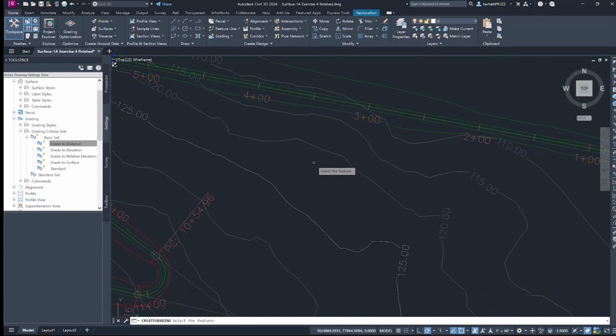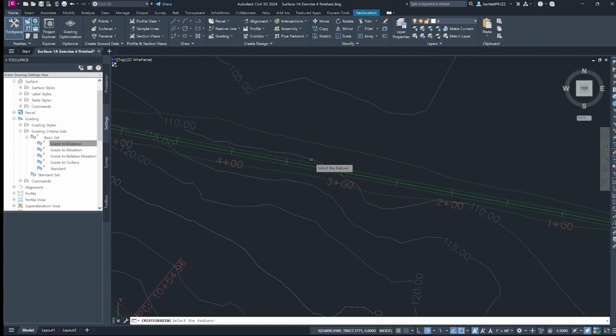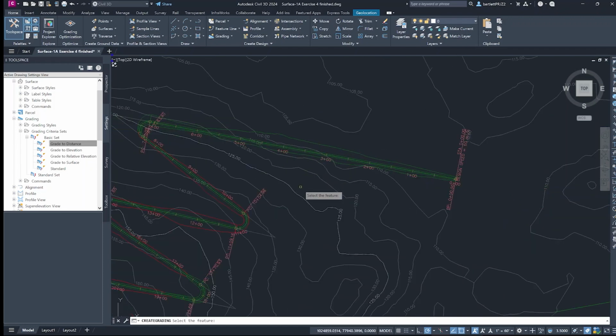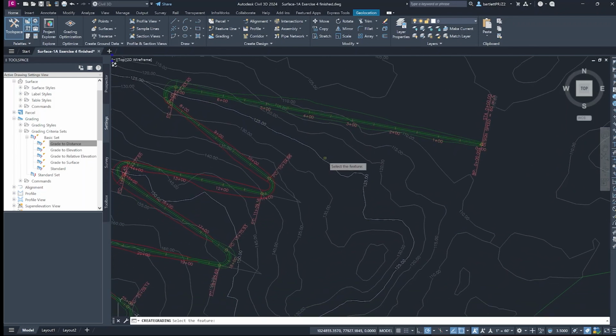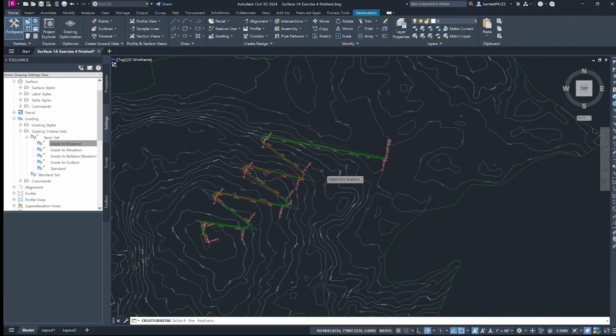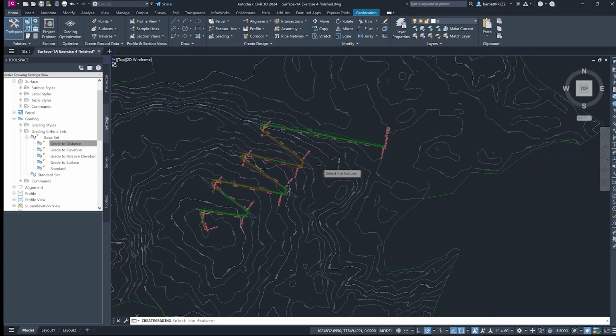So these are where you can think of this from the shoulder of the line out to that line. If this is a fill slope on a 2 horizontal, 1 vertical, is where that slope would catch the existing slope. So that gives you the widths or dimensions of your cut and fill as you go on. Of course, then you can also ask the program to give you your cut and fill quantities. So that concludes this. This is what you would do for your homework also.